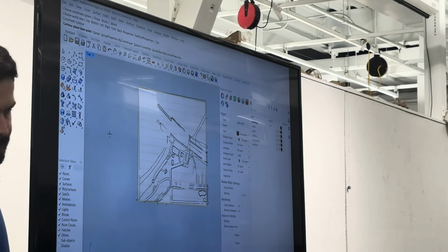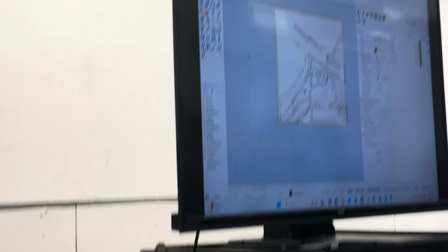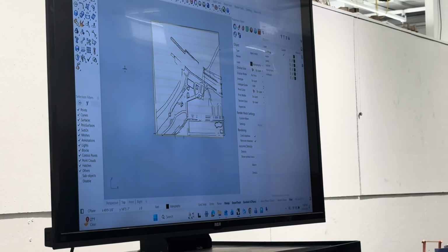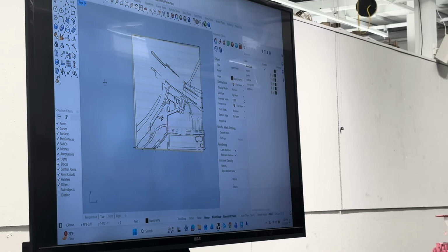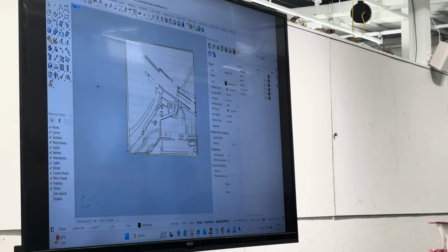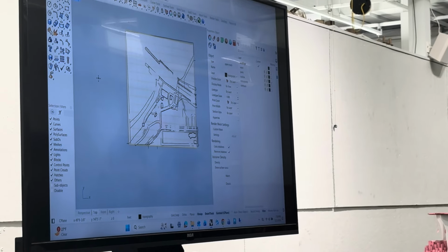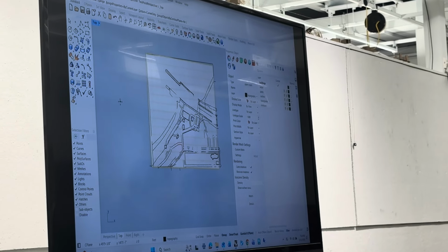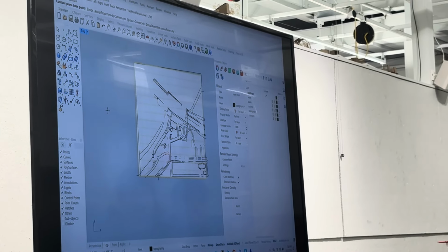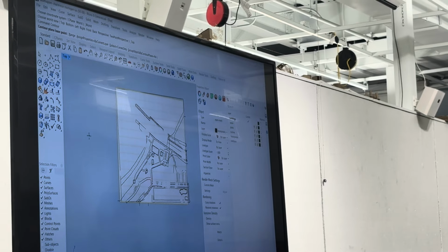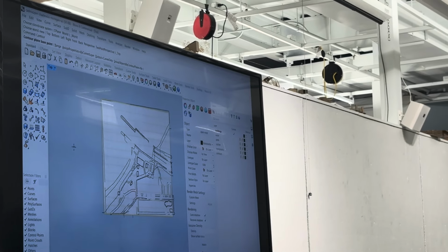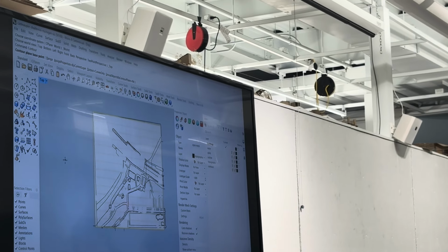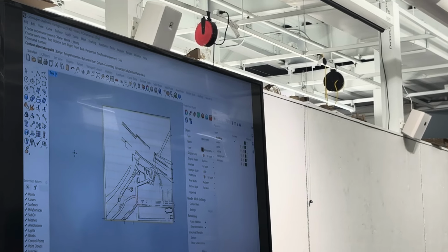Depending on the stepping of your topography, you're going to determine the thickness of the material that you're going to use, and then you use that as the distance at which you slice your site file. So if it's after you scale it down, your contour should be every 1/8 of an inch, or 1/16 of an inch if you can get a smaller condition. These all can be converted into laser cuttable files, which I think you went over Monday.